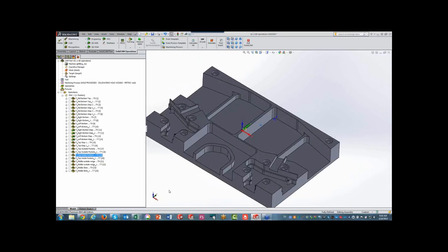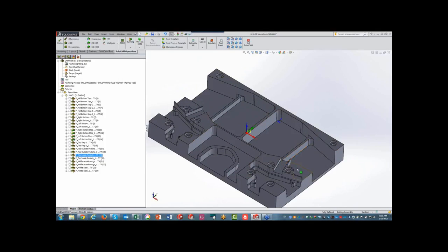I can go on just for a moment. You'll see I also have this area over here. So I had a separate operation for that. And we also had these slats over here. I had to do a separate operation for that. I had a total of 24 different operations for the roughing and the finishing using the standard 2.5D operations with 12 different geometries. I had to create 12 geometries, 24 operations.